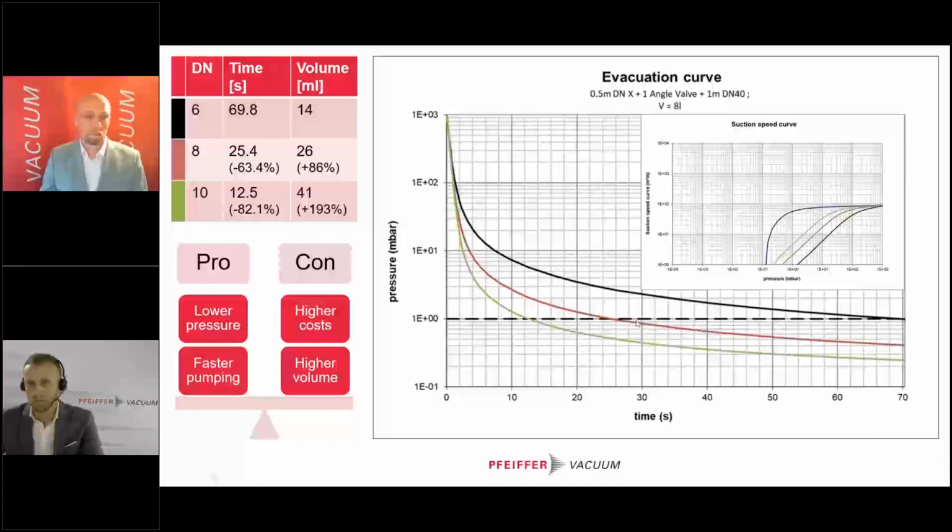Let's say I have 100% helium inside and evacuate down to roughly 1 millibar and fill it with air and then open the connector in my chamber. Some helium can exit my part and it goes into the system. Now, when pumping down lower, half a decade, we have half the concentration which enters my system, which is of advantage considering a helium contamination of your system.